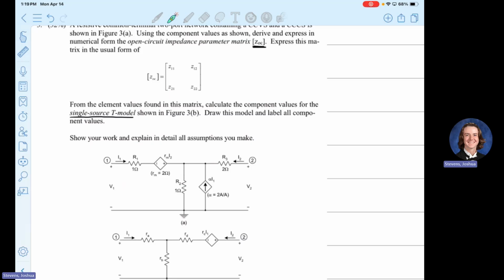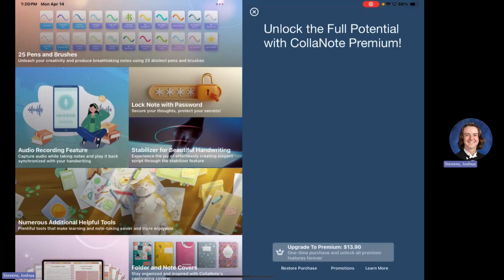What does that top network kind of look like? What are some tools you think you could analyze that from? Just like you use MESH, you could probably use NODE. Well, what does MESH need? You need voltage sources, you need resistances. Or you could use NODE, which is conductances and current sources. Well, we have these two voltages here, theoretically a voltage source. We have this voltage source here and we have this current source here. Okay.